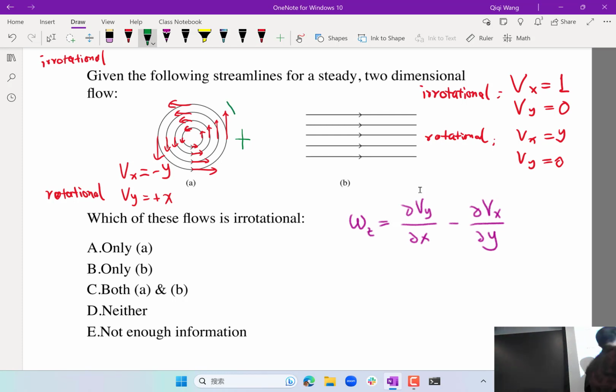So the vertical line, if it's a very small segment, almost follows the streamline, and that's going to keep following the streamline. So it's going to curve basically like a circle. And the horizontal line, because the outside is faster, is going to curve in the same way. It's going to become like that, right? So it is exactly what we discussed when we defined the material line definition of vorticity.